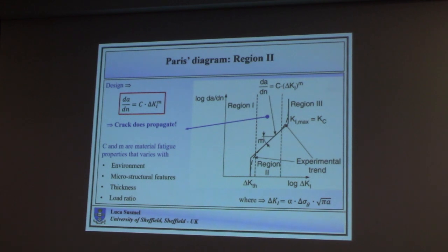Cycles can be days. I don't know, if I have a chemical process and I need 1,000 cycles a day, and my crack needs 10,000 cycles to propagate, I would say, ooh, I can work for another 10 days and that's it. So it depends on what your units are, but in the end it's the lifetime you want to measure, and it depends on your specific application.